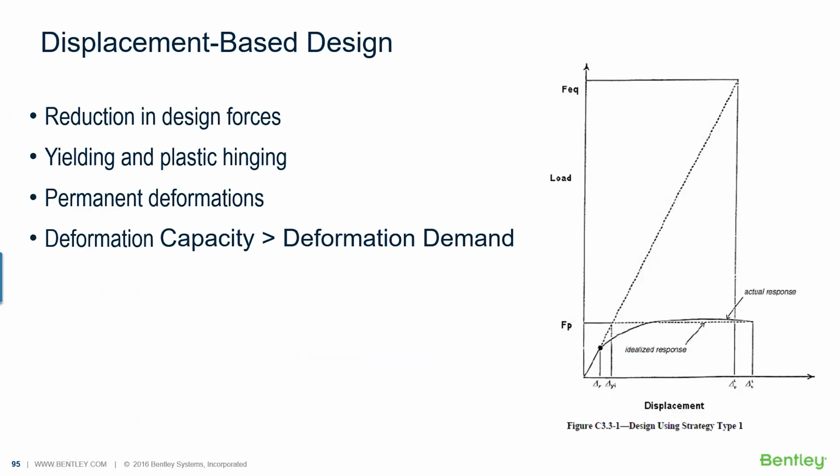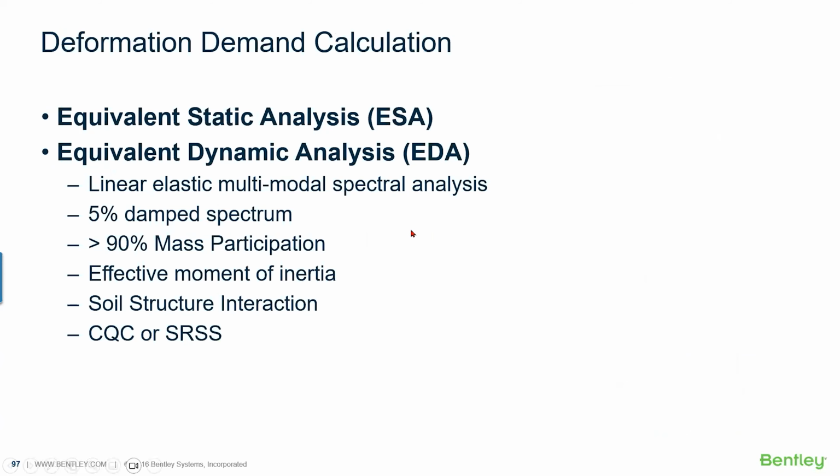We can also use displacement-based design. So compare the capacity with the demand. This is very useful, very quick. It's a nonlinear analysis and gives a very quick answer compared with step-by-step analysis.